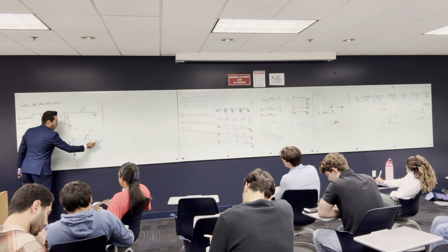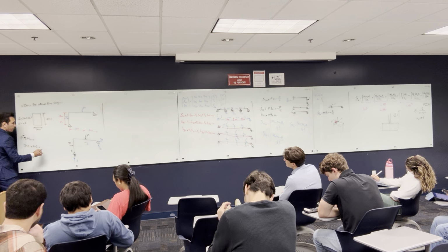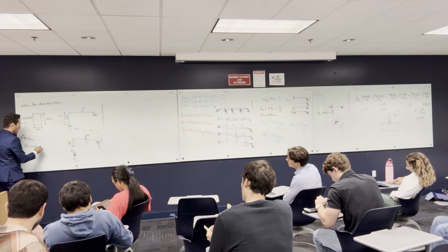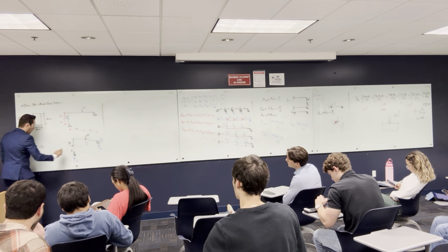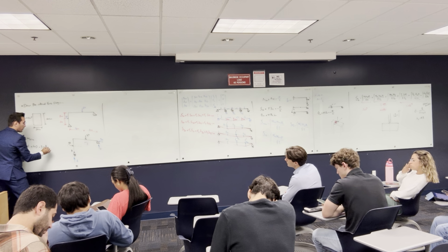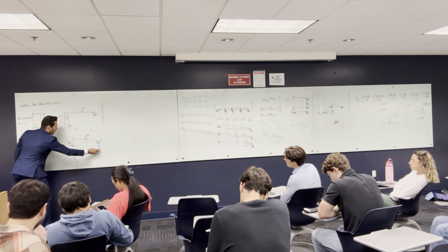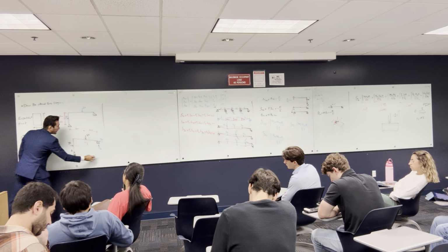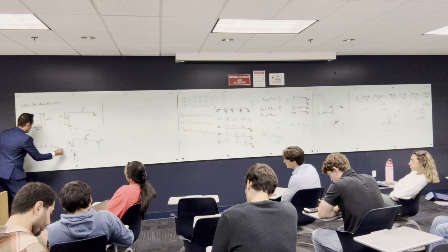And this minus, you have a 3 here, so this 3 is gonna be minus 3 multiplied by 4, and this one is the reaction that I'm looking for, so this one is gonna be negative, the reaction, let's say, y, multiplied by the distance, which is 6, equal to 0.